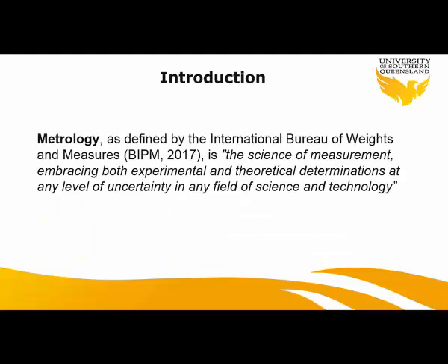What is metrology? Basically, metrology is the science of measurement. We want to measure devices or industrial machinery, or it can be a ship or aircraft. So the measurement here needs to be very precise, let's say better than 1 mm at 95% confidence level. So this is the general or more simplified version of metrology.